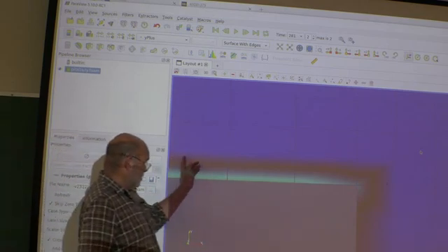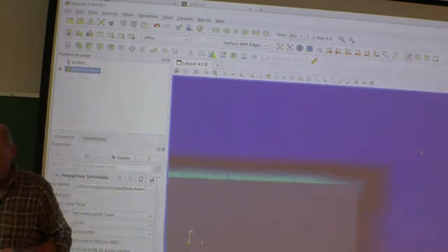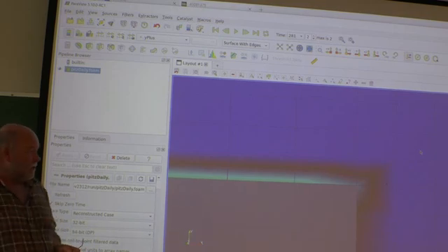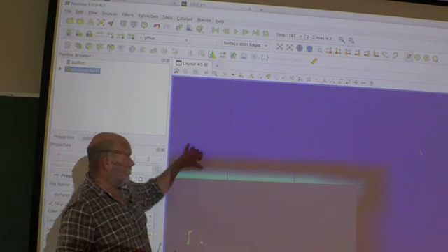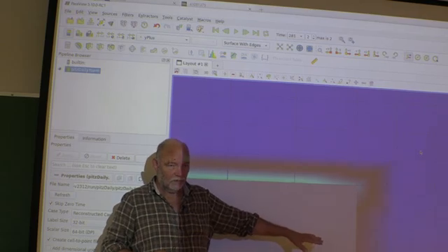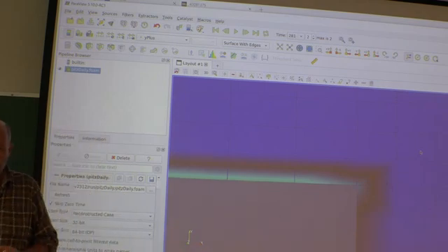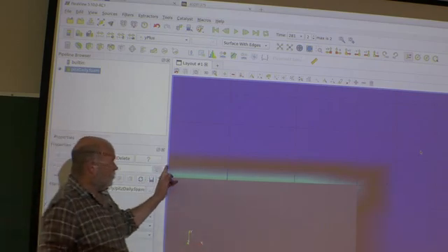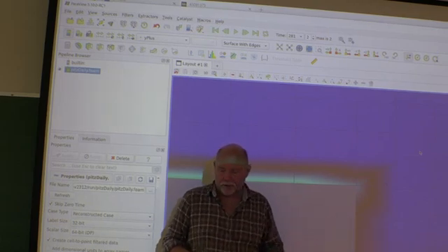So the mesh here, no, it's not good. If you want to use wall models, then I would say this mesh is too fine. We should reduce the number of cells. We should have bigger cells alongside the walls. Here we are on the limit. I mean, it's not that far from 20 or 30 down to 6. So it should be possible here to resolve the boundary layer so that we can have more natural boundary conditions.